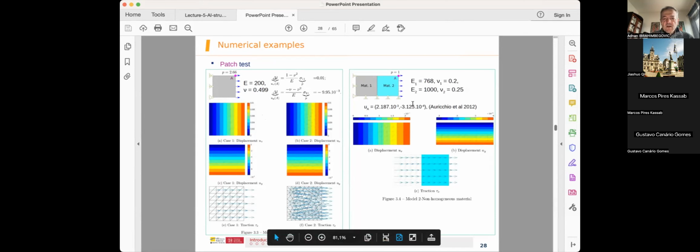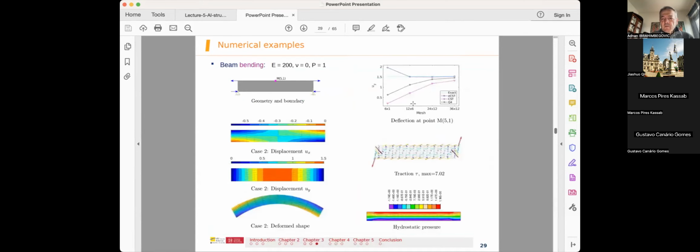Again, you can pass that without any problem. And then this is the bending. Again, this element is really perfect because first it converges from above, and it gives you very quickly quite an excellent result already. The coarse mesh here, 12 times 6, or the coarse 6 times 1, is giving you a sizable better result than any of the others.